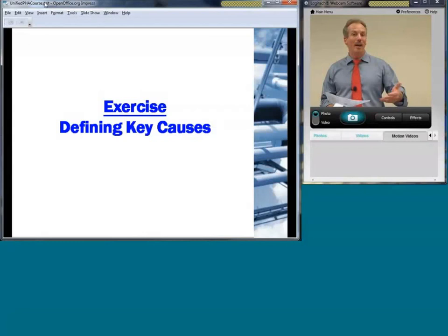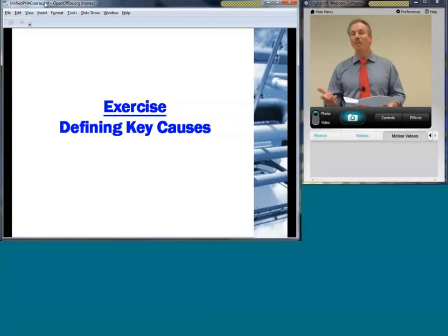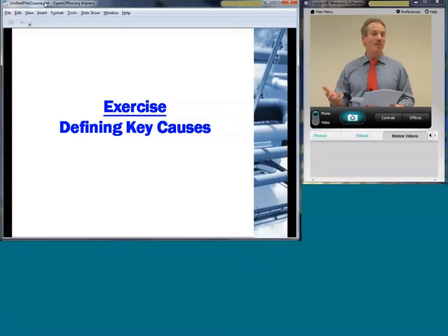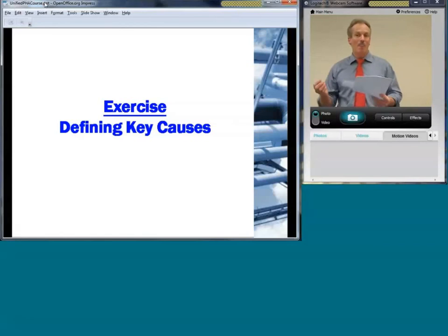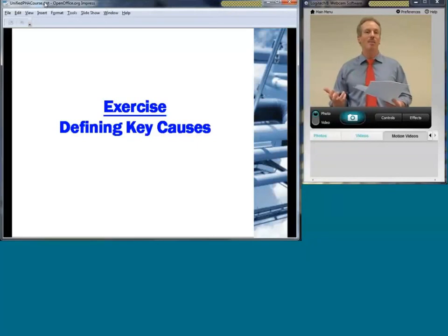Well, this is really a very simple one. The major active component there, and by the way, another thing you need to do for a HAZOP study is separating the important from the unimportant. On this diagram, there's lots of valves, there's lots of manual valves, and there's also a lot of valves that are shown for instrument loops. But recognize when you're looking at a valve on a level bridle, closing that, compromising that, it's going to have the same effect as if the level transmitter fails. If you're looking at a level control valve, that valve closing is going to have the same effect as if the block valve is closed. So combining those, simplifying it, and looking at the things that are really important is absolutely critical.